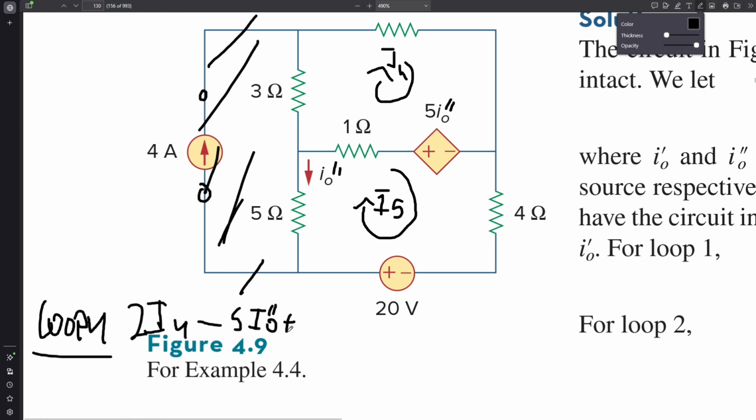Now that will be plus I4 minus I5. It could be in brackets, it's multiplied by 1, so basically the same answer. Now for this one, I4 times 3, so plus 3 times I4. Because remember, this is an open circuit on the left, so there's no current from the left side. And now they'll all equal to 0.